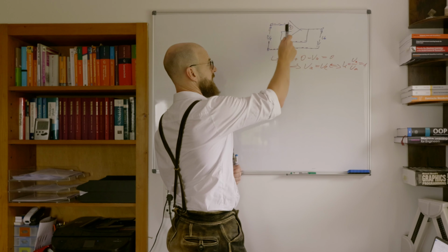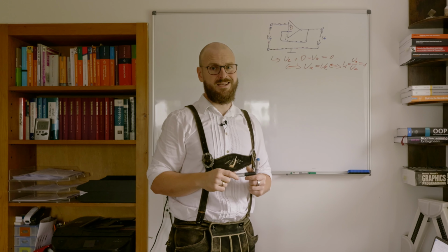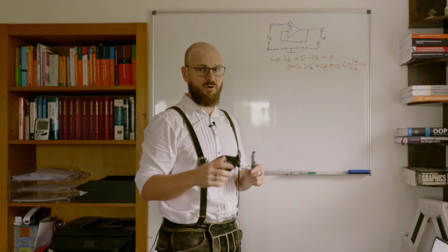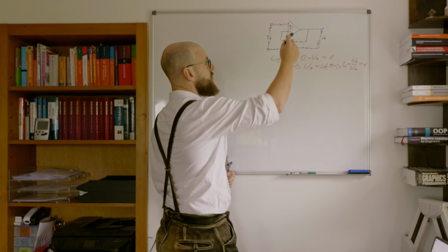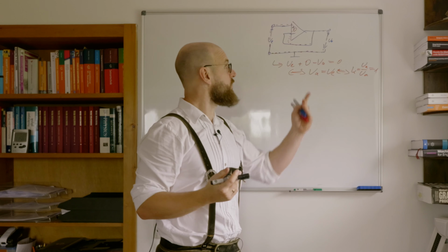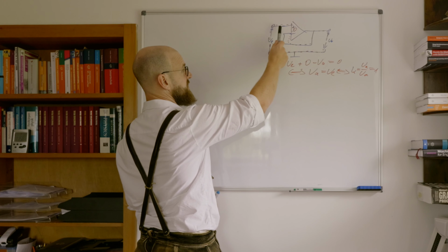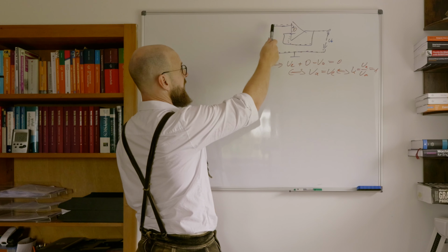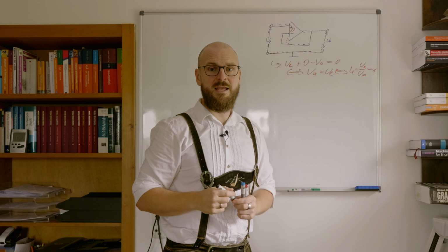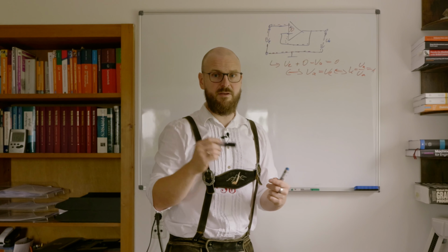We know that the operational amplifier has a very high input resistance. And now, doing some electrical calculations, we won't go into details about, but doing the feedback loop over here, the input resistance of the whole system, so the resistance which is seen from the input where UE is connected to, even rises more by recoupling, by doing that feedback loop.